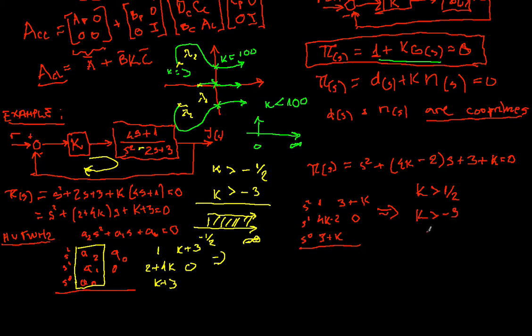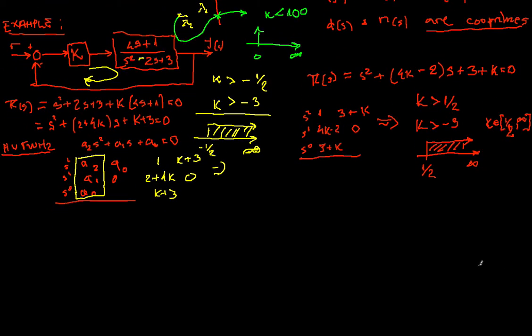As you can see, the range of the available gains that can stabilize the closed loop system when the original system is unstable, like in this case, is already smaller than in the previous example. So here k is going to be all values from 1 by half to infinity. So the gain, still a pure gain, goes from 1 by half to infinity. Okay. Interestingly enough, we are still dealing with a simple gain.